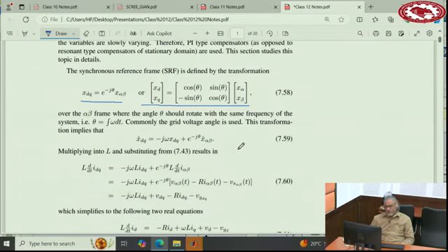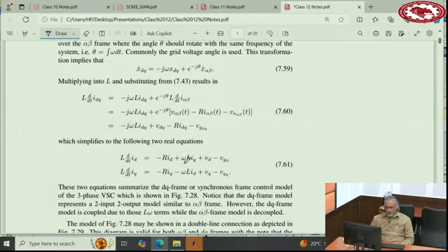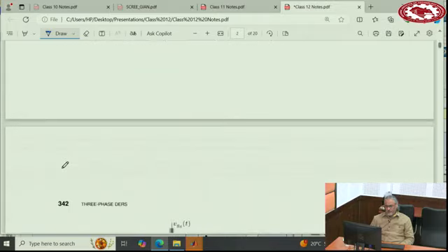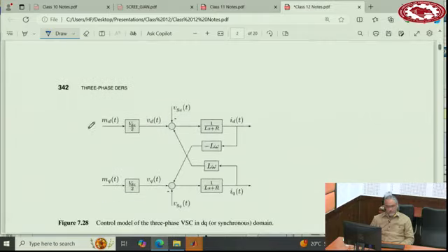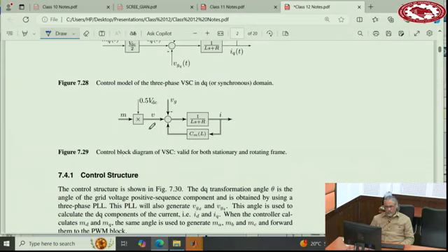And once mathematically defined, you can derive the equations of the converter, and the coupling terms obviously are there. These are the coupling terms. And also we use this vector notation or matrix notation that we have, very convenient. And by the way, this notation here is very nice because if you put this equals 0, this is valid for alpha beta.